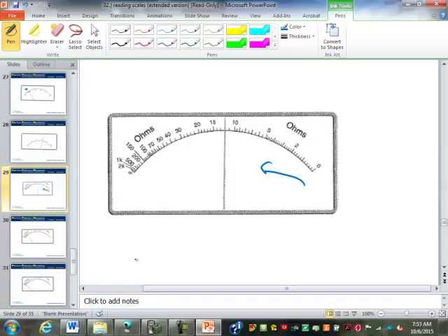And so a lot of the old meters worked on materials where, if the material warped based on something happening, like your old thermostats, which were two metals pressed together that would warp as they heated up because one expanded faster than the other. Similar types of things in a lot of these meters were based on physical reactions to an electrical phenomenon. And because of the physical reaction of that material, it changed. The higher the resistance got, the less it started to move. Rather than adjust the material to make it react in a linear fashion, they just adjusted the scale to make it match up with whatever the material did.